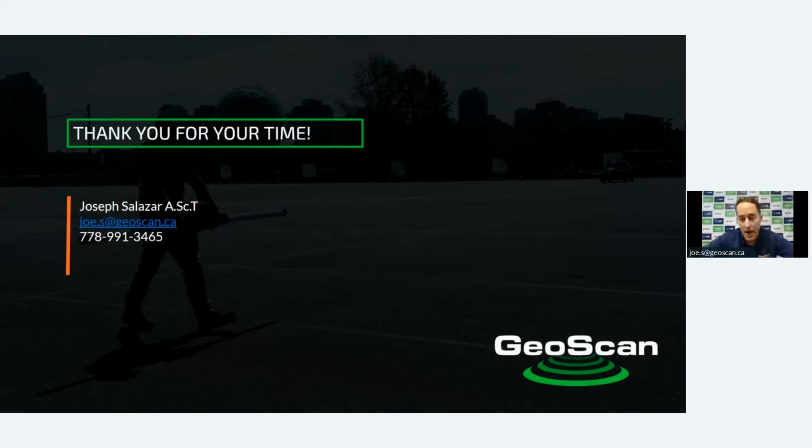Essentially, radar travels through different materials at different speeds. So as it's going through soil to concrete or to air, that change in speed is picked up by the data in the control unit, and that's what the technician's looking at. And unfortunately, as it hits saturated soils, that data just becomes illegible. Sorry if that was a poor explanation, but there's some science behind that.